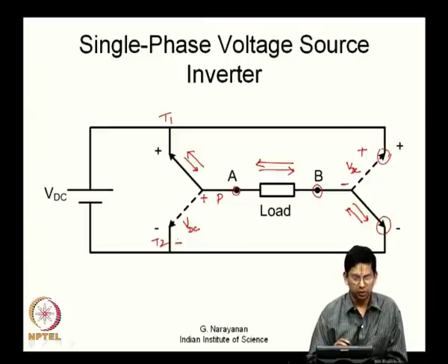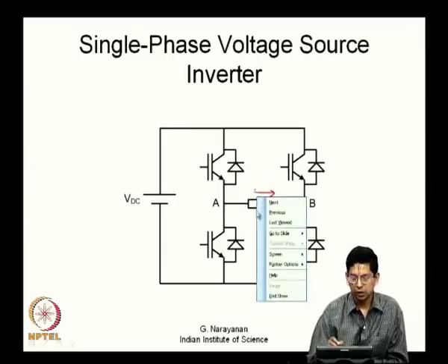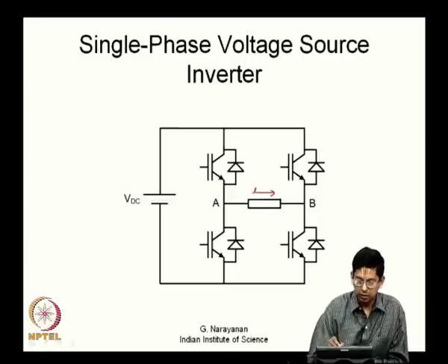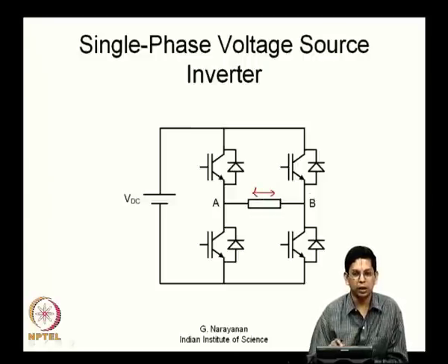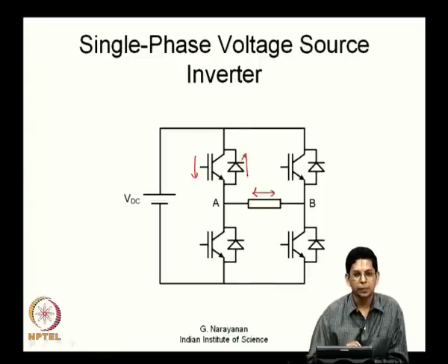So, you want to come up with a particular set of electronic switches now. What you do is you can have a switch like this. So, you can have a bidirectional conduction here, in any direction the load current might be flowing. If the load current is in one direction, the transistor will conduct. If the load current is in the opposite direction, the diode can conduct. And let us say this switch is also on. Correspondingly, depending on the load current direction, the transistor will conduct or the diode will conduct.